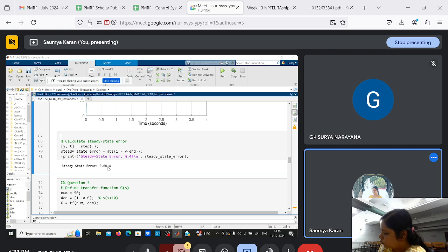What margin you have before you are going to reach the verge of instability? Your phase margin indicates how much phase can decrease before instability occurs. So how do we make sense out of them?